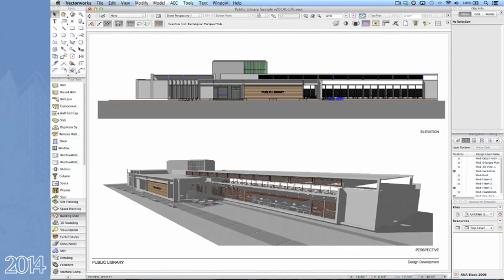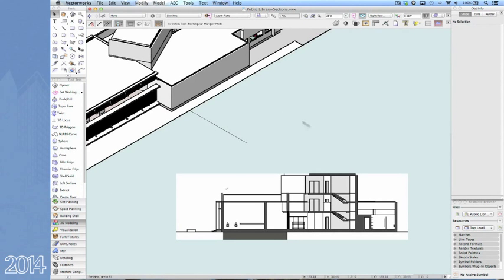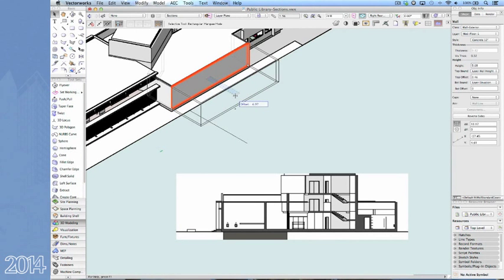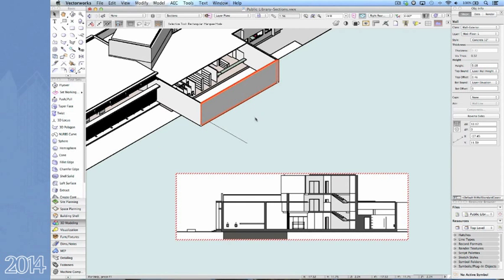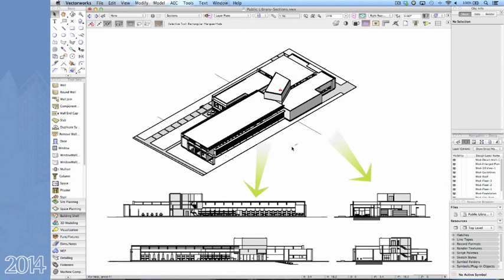Flattening your design layer section viewport also lets you create additional views within a single design layer. You can now make changes in your model and see those changes reflected in section just by updating your flattened sections, rather than having to navigate to multiple sheet layers. These improvements to section viewports will help you create an efficient and intuitive workflow for modeling and documenting your project.